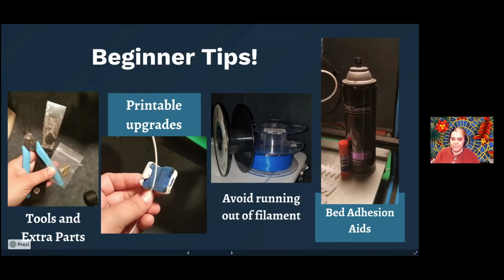And then if you have trouble with your print sticking to the bed, glue stick. Glue stick number one, hairspray if you've got it. I don't like using it because it makes my office stink, but I've got hairspray for when I'm really frustrated and I just want to shoot it with hairspray. So I recommend that, especially if you've got a glass bed.